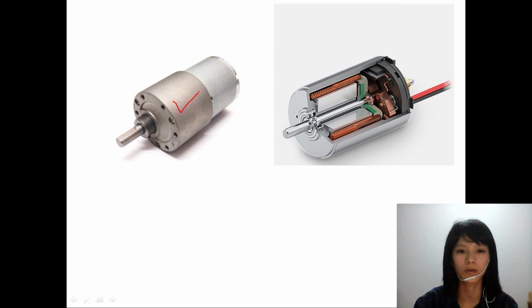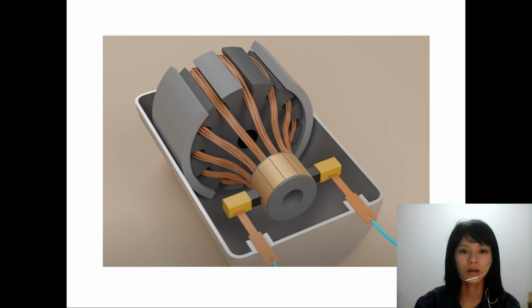So this is what a 12-volt DC motor looks like. We have drawn about 100.7 millimeters of length and 98 millimeters of height. There are the shaft, front motor, back motor, motor can, and the stator, which always provides the stationary electromagnetic field, and the rotor, which keeps rotating due to the induced EMF. For the rotor, as you can see here, there are many teeth, which is where the coil winding is placed, and there is a commutator and brush.